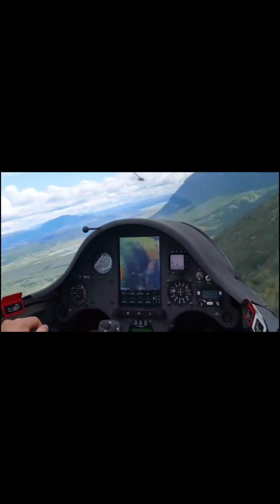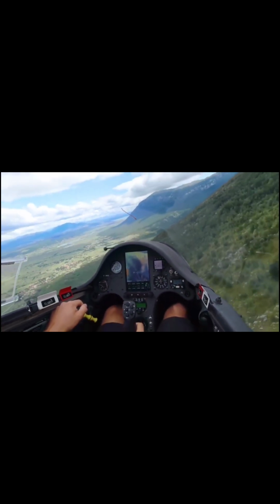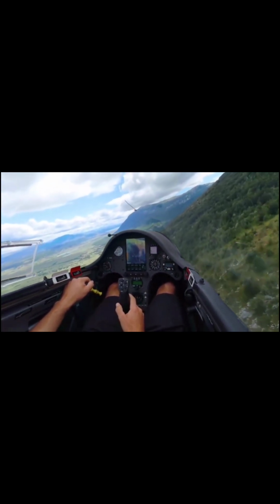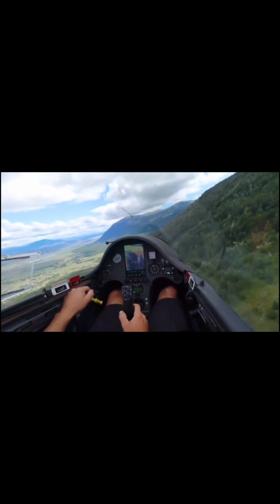The variometer indicates the speed of climb and descent. This instrument is super important to know when the glider is beginning to climb, usually when it enters a thermal, and thus stay within the thermal. The gliders are equipped with a system that generates a sound depending on the speed of ascent or descent. With this sound, you can more easily identify if the glider is going up or down without having to look at the indicator at all times.